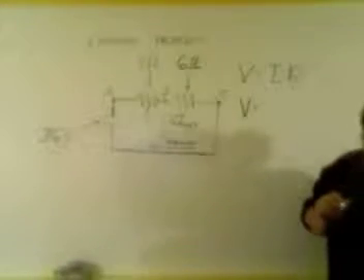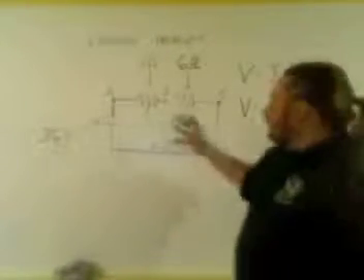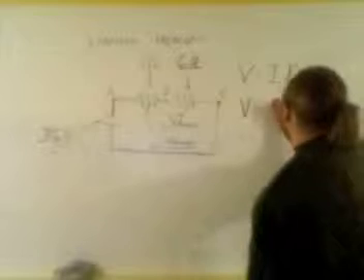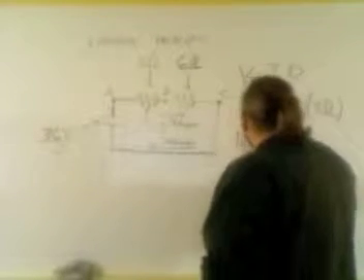And what was the current that was going through that resistor? What was the current there? Well, it's 4 amps, sorry, not ohms. 4 amps is 4 through the entire circuit. So it's 4 amps. And now, we're not concerning ourselves with the entire circuit, we're only concerning ourselves with one portion of the circuit. So what's the resistance for that one portion of the circuit? 3 ohms. Okay? So that means that my potential drop is 12 volts.